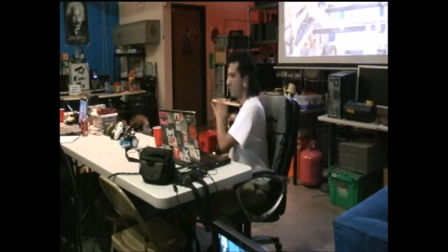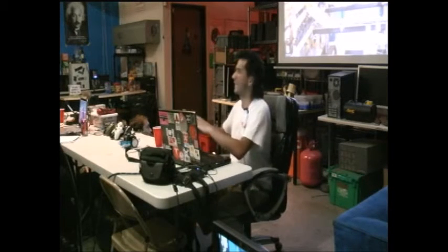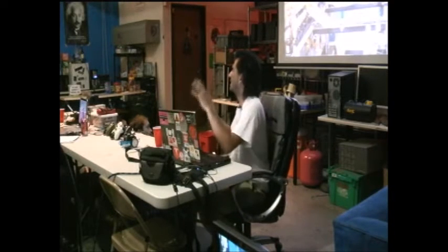The overarching topic of what we're trying to cover here is that you, the human, are the noise filter in all of this. The computer can do a lot of stuff automatically on its own, but you have to apply context and consider the noisiness of the image to what you're trying to scan. So if you can get optimal lighting and eliminate as much of the background out of the image as possible, the reconstruction will be nearly perfect.